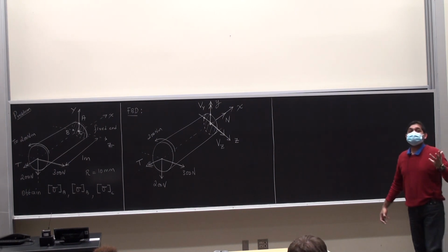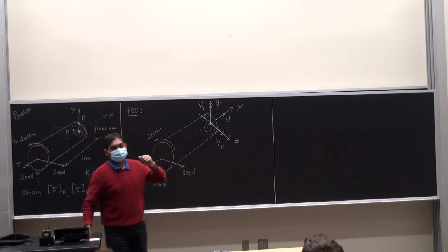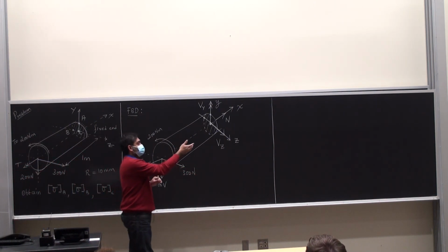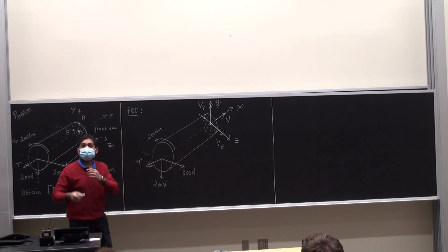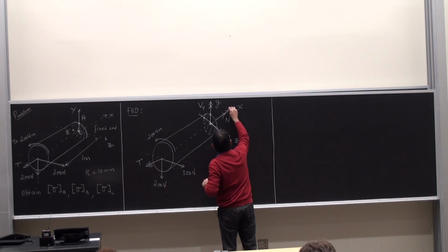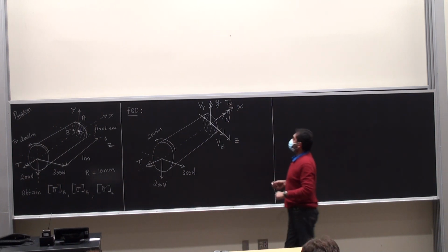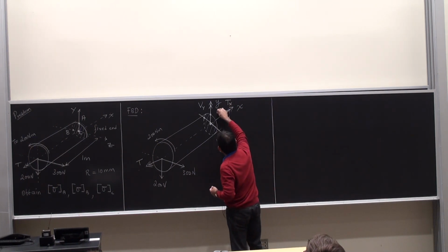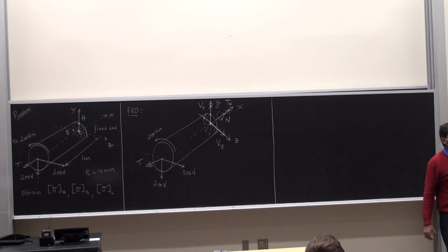I'm going to have 3 reaction moments, out of which one is a torque. Okay, so watch this. I'm going to have a reaction torque at the fixed end of the shaft, like we have been doing for torsion problems. Okay, so that's going to be double arrows here. I'm going to call it T suffix x. If you want, you can also draw the curly arrow signifying that, but there are too many arrows and it makes life very miserable.